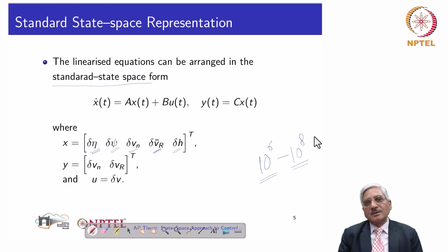So it means that the neutron flux density measurement has to be carried over about 8 decades or minimum 6 decades. This is an enormous range, and this enormous range is not possible to manage by a single set of instrumentation and amplifier.